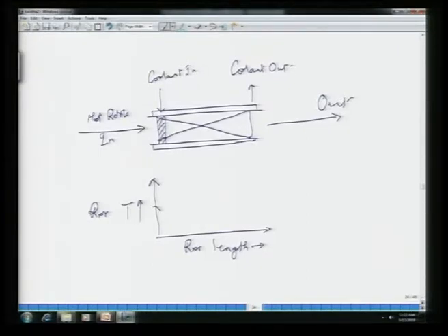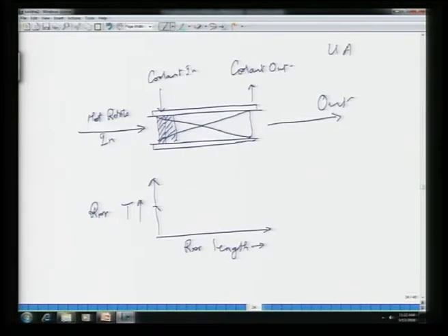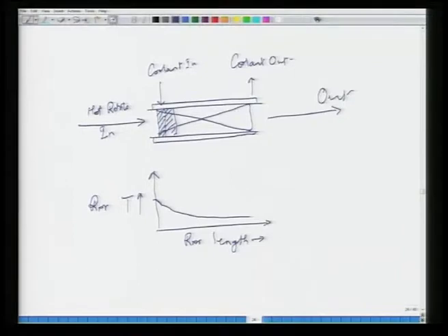Now, because the temperature has gone down, if I move to the next plug, which is here, and I am just blowing it up, the next plug sees a lesser amount of reactants because some has reacted, and a lower temperature. The amount of heat being transferred will be more because heat transfer is governed by UA delta T. Let us assume that the coolant temperature is constant, say the coolant flow rate is very high, so that the temperature the tube sees on the coolant side is essentially constant. So, delta T is T reactor minus T coolant. Now, your T reactor has gone down. You are removing more heat than is getting produced by the reaction, and therefore temperature actually dies down. This is called the quenched state.